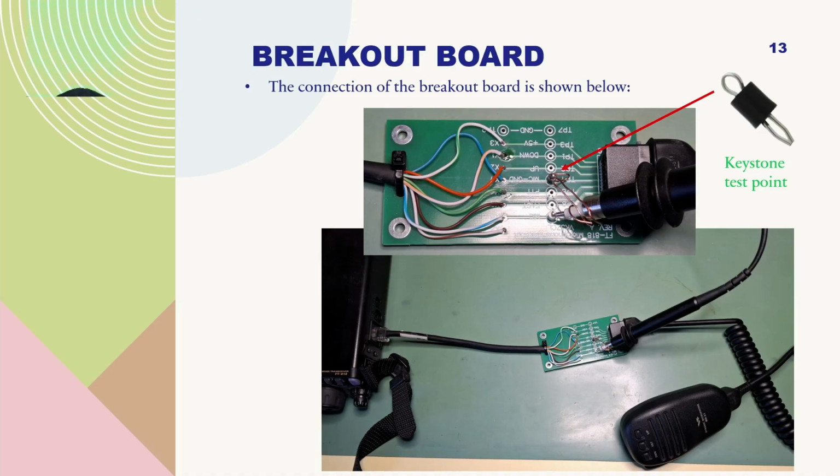There we go. It's literally just an RJ45 patch cable, a network cable that I cut and soldered onto the board, and then just put an RJ45 socket. And then onto that board, I just soldered on some keystone test points. They're these ones here, really good. You can get your crow probe into the end of them, or a multimeter tip, whatever. And that allowed me to measure the level using the oscilloscope probe directly on this board.